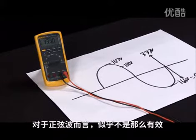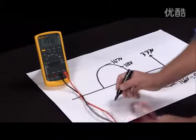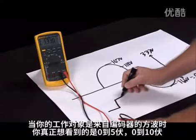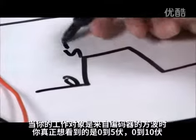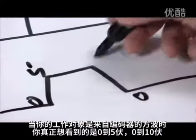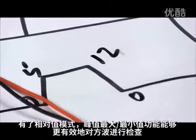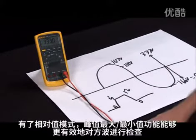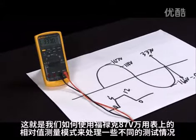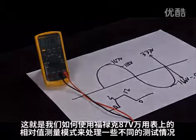For a sine wave this might not be so handy, but when you're working on a square wave coming off an encoder, what you really want to see is: is this 0 to 5 volts, or is it 0 to 12 volts? By having that relative mode and the peak min max, you'll be able to check your square waves a whole lot better. So that's how we can use the relative mode on the Fluke 87 to troubleshoot a number of different situations that we're working on.